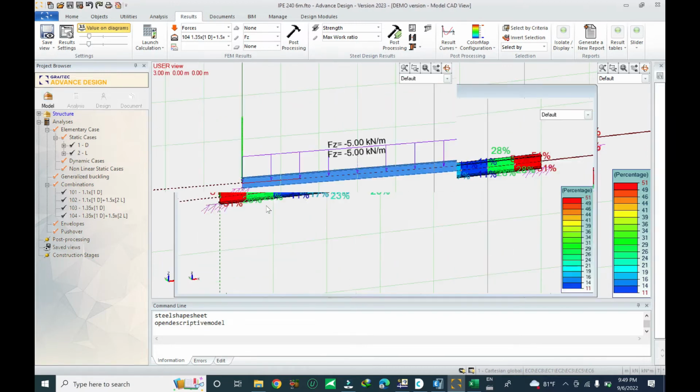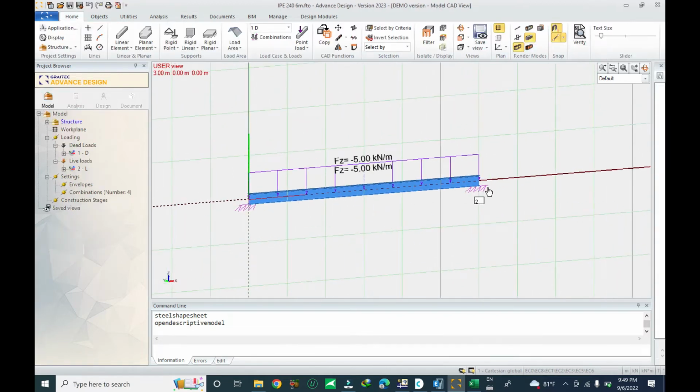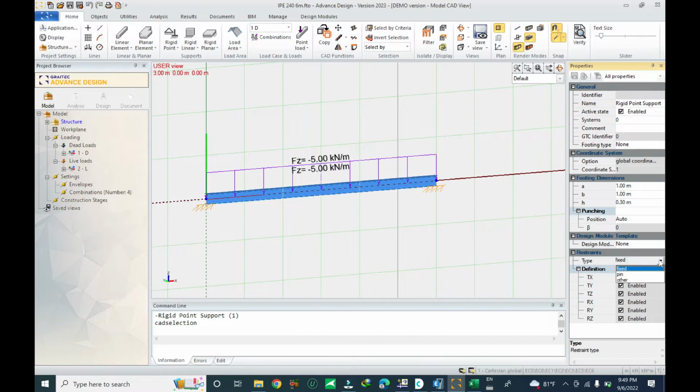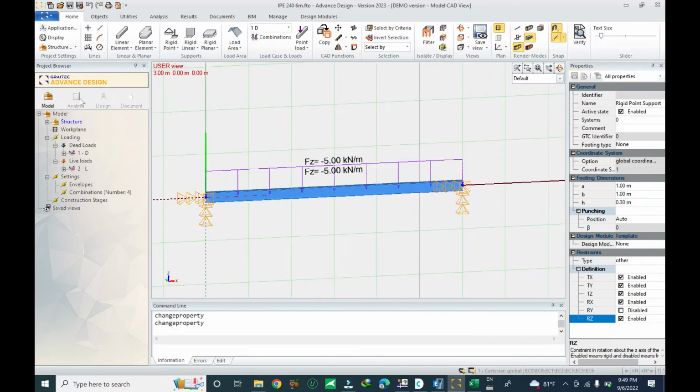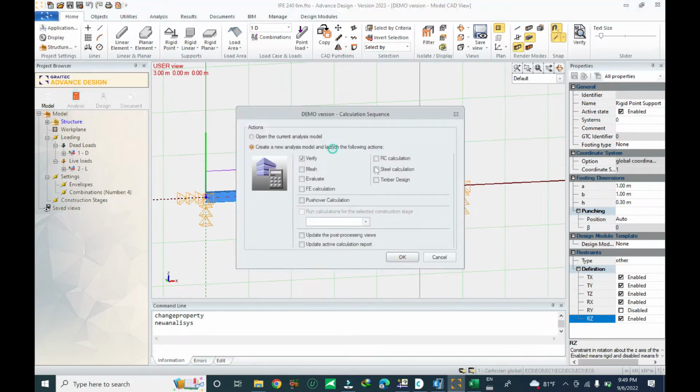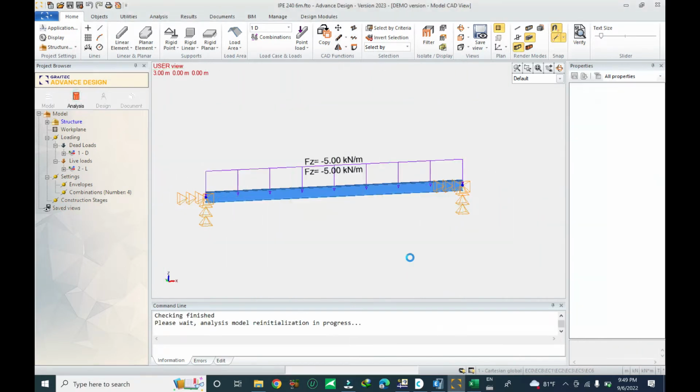Okay, now let me click come back. I want to change the support, and we will check together whether the parameters of the beam change or not, whether parameters C1 C2 change or not. Okay, let me click on this one and change the fixed to other to make sure our structure is stable. Okay, now come back. We keep everything the same, but we have to change the support condition. And let's check the steel design again. Run analysis and design.